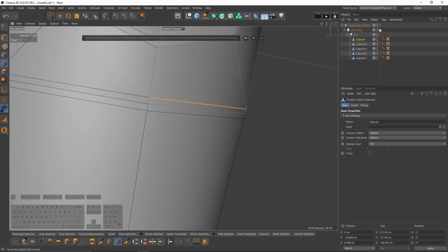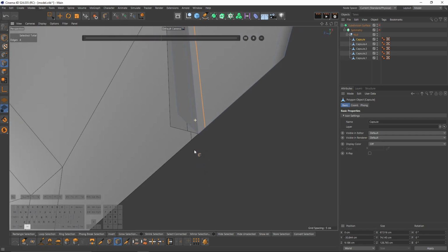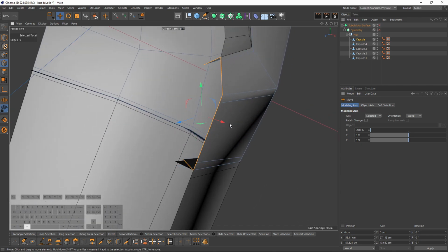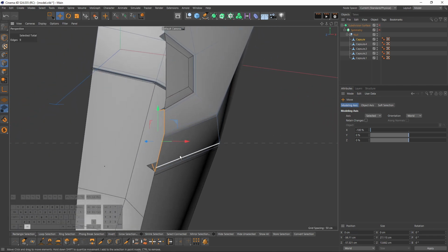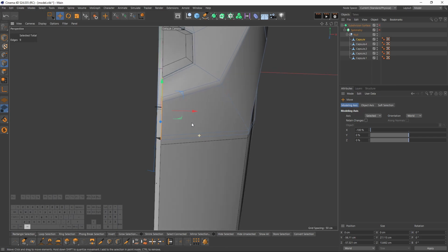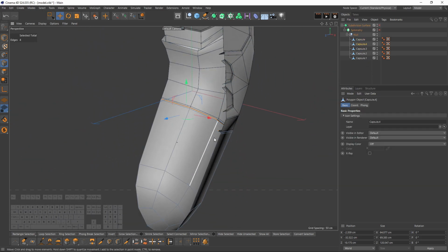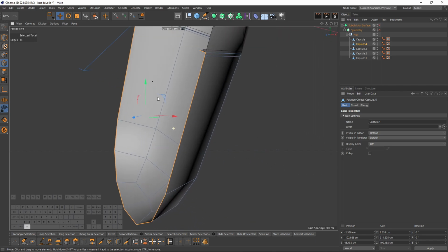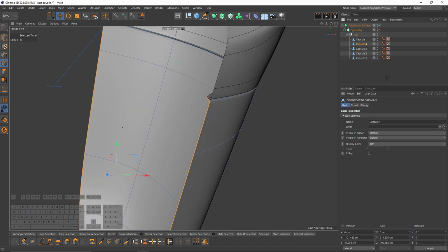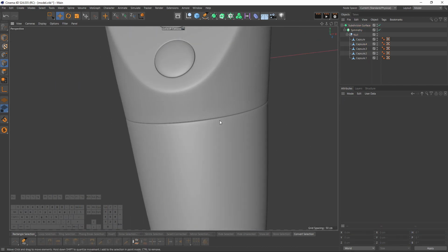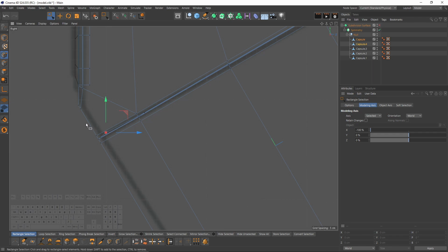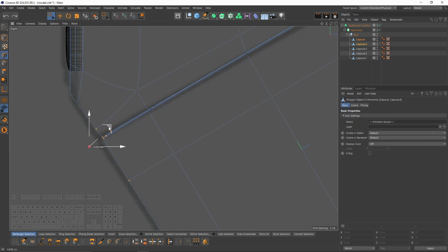So it looks like I have some problems here. So I'm gonna double click on these edges, set their position to 0 and also size. But I see that they are already on 0. So let's do the same thing for these ones. Set to 0, size and position. Yes, now it works. I will select them both, select these points and move them just like that.